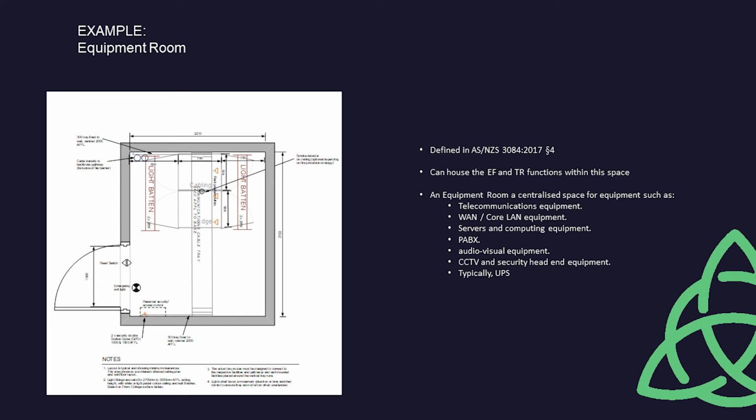To calculate this will require the confirmation of the power consumption per equipment rack space, where data is unavailable. As a rule of thumb, the minimum allowance should be based on the total maximum cooling capacity to meet or exceed the peak solar load plus 1,500 watts per equipment rack and rack space. The air conditioning unit must blow cold air into the aisle in front of the equipment racks whilst drawing return air from above and behind racks. We recommend the adoption of a hot aisle, cold aisle philosophy.